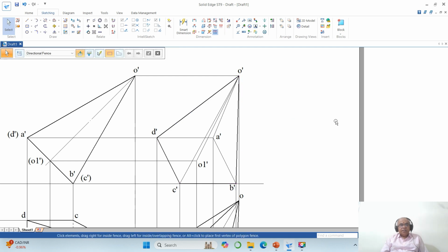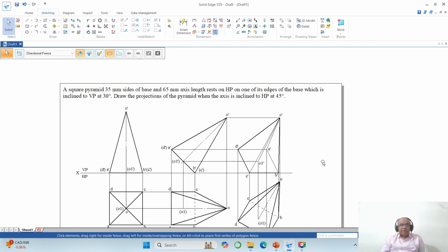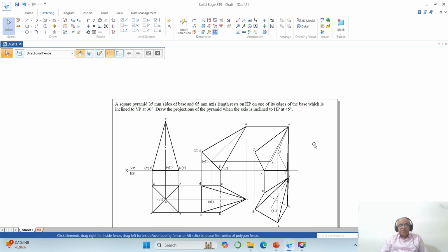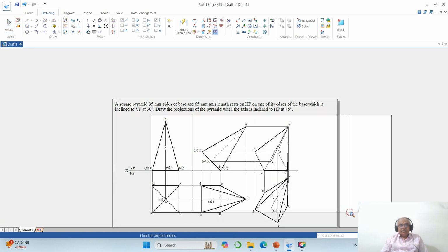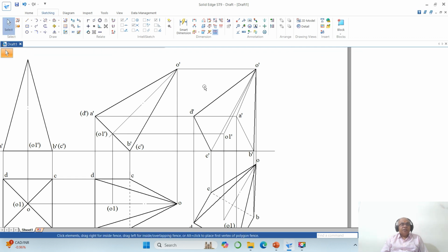First thing. Then the surface nearer to the observer, it is visible. That is ABCD is the bottom surface, which are all the edges which is near to the observer are visible. So I will select these two now. Then you go to 0.5. From a point, that is from A dash, D dash is visible and A dash, B dash is visible. Therefore, O dash, A dash is also becomes visible. You make that edge 0.5.